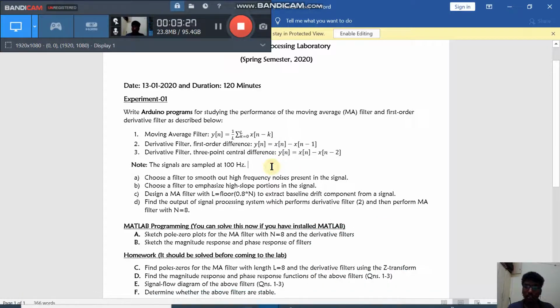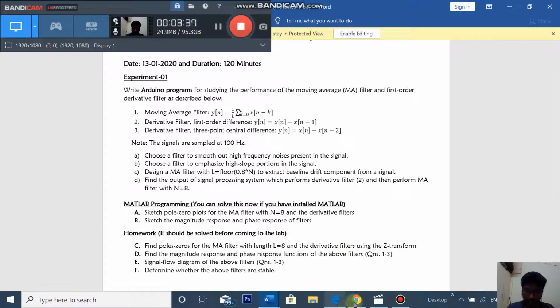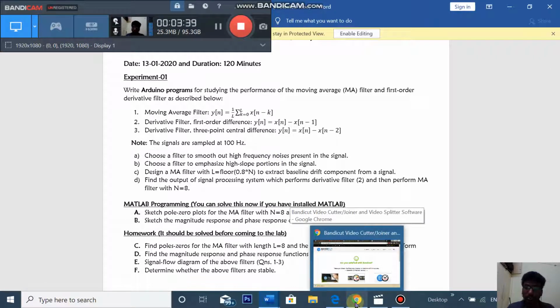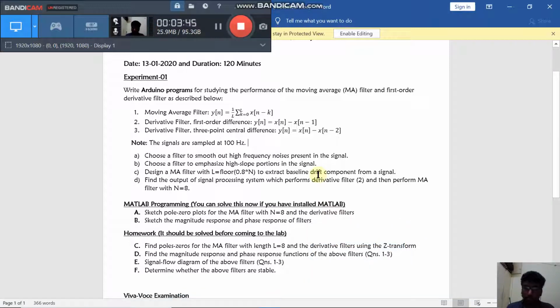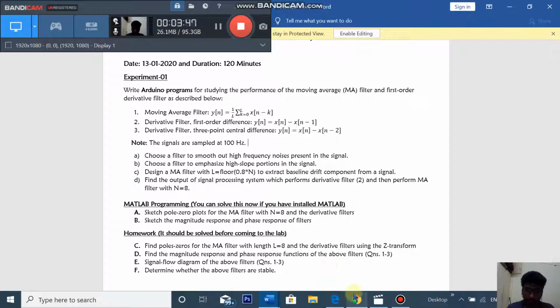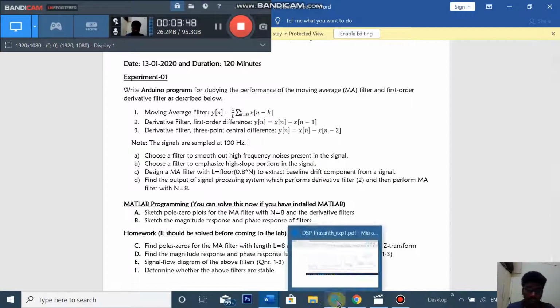It's just a high pass filter. The difference of the present input and the past input becomes the output point. It is also known as the backward difference filter. Now let's look into the code.